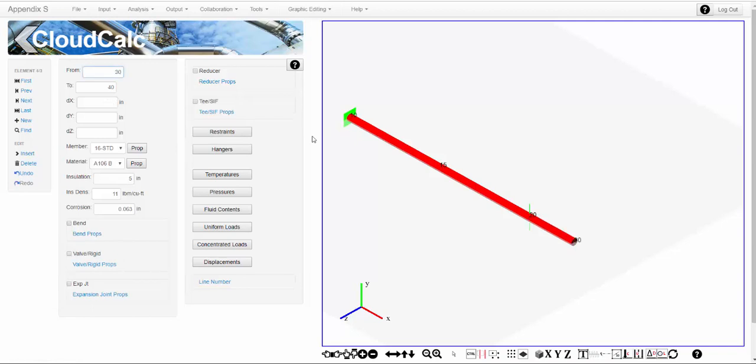So we continue. Next, we're going to move up in the Y direction, 20-0, 20-foot 0. Again, we have a bend there. See the skeleton moving up, so it confirms you're going in the right direction. Again, defaults to long radius bend, 2 intermediate node points, as we expect, and we hit page down, and it processes. Now we can close this.